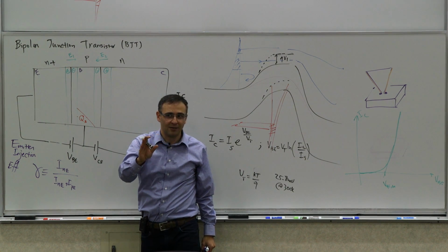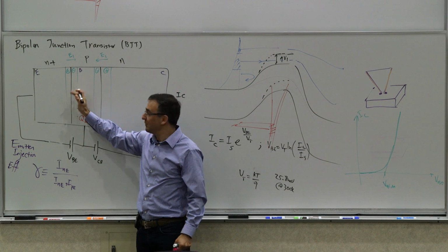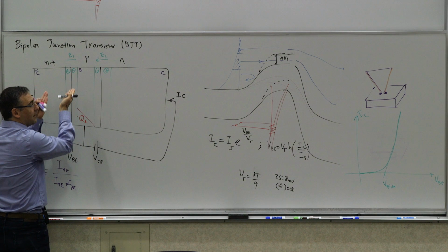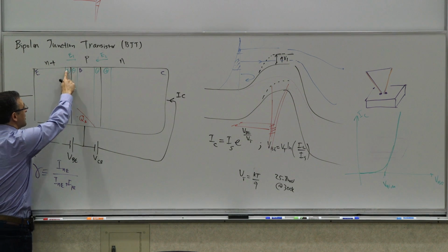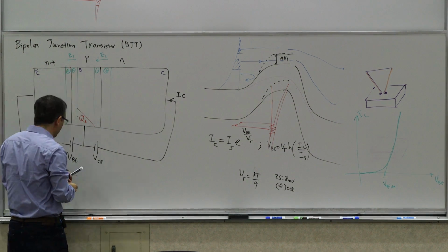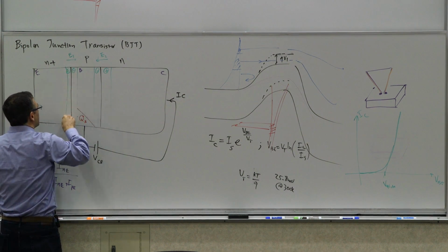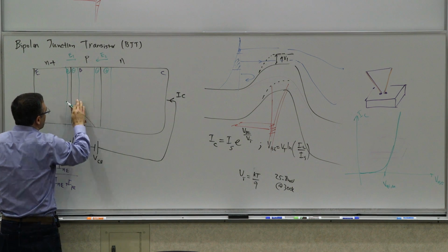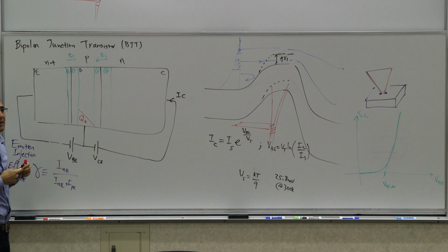One was this resistance. Two, but we can say, okay, fine, but it doesn't matter. I raise the doping concentration of both of them at the same time until I get the right resistance. Okay, fine. Two is this depletion region, because now, if I have that kind of concentration, the depletion region will be mostly where? On the base side. Yep, it does happen, and you live with it.